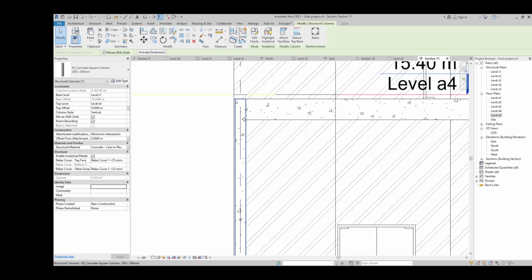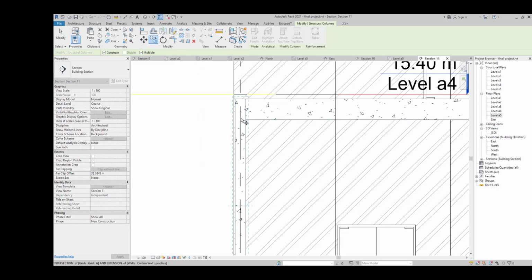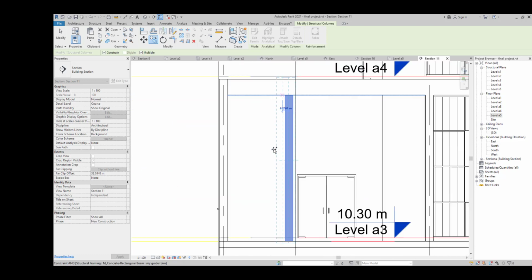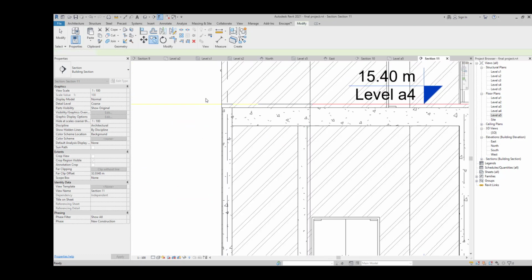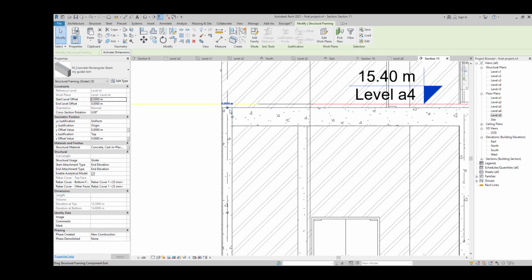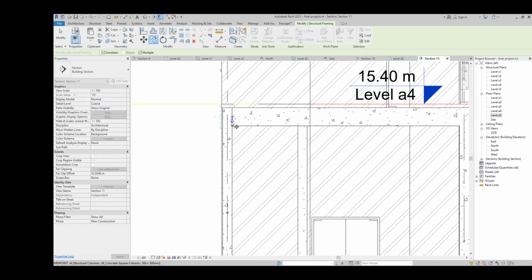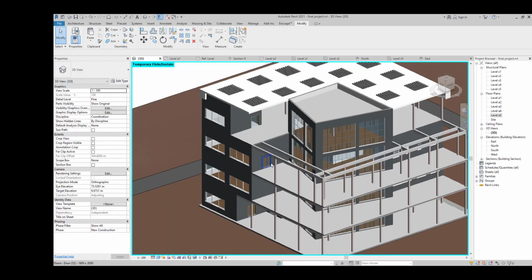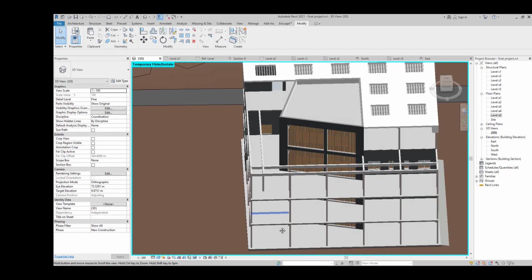After that I'm just going to use the copy option for 2 meter, and the next step is to select our beam system as well. So I'm just going to click our beam, CO, select the corner and here. Then we are going to check our design, so everything looks fine.